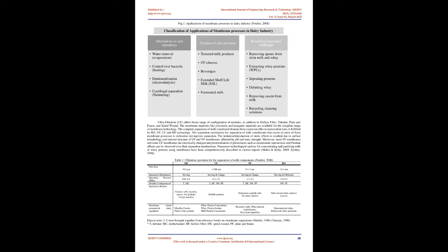The widespread filtration spectrum of membrane processes applied in the dairy industry is reviewed in Table 1, that includes microfiltration, ultrafiltration, nanofiltration, and reverse osmosis membranes. These four membranes are classified by pore sizes that vary between greater than 0.1 µm and 0.1 nm and operating pressures from 0.01 to 5 MPa. Nanofiltration, NF, and reverse osmosis, RO, membranes require higher operating pressures compared to other membranes.